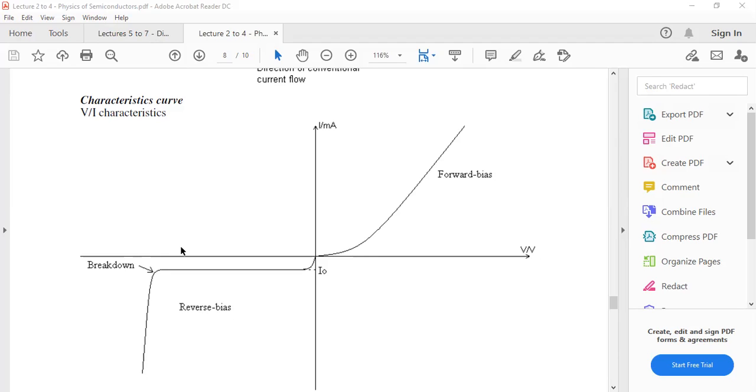Okay, so this highlights a very important discussion, the difference between a normal diode and a Zener diode. Just to recap, a normal diode would blow away when you operate it beyond the breakdown voltage because of a sudden increase in current causing heat dissipation. But a Zener diode is able to operate in this region as long as we don't exceed the power specification that's specified on that specific diode. We're going to look at that in a few minutes. So I'm shifting back now to the slide for the Zener diode, and we proceed.